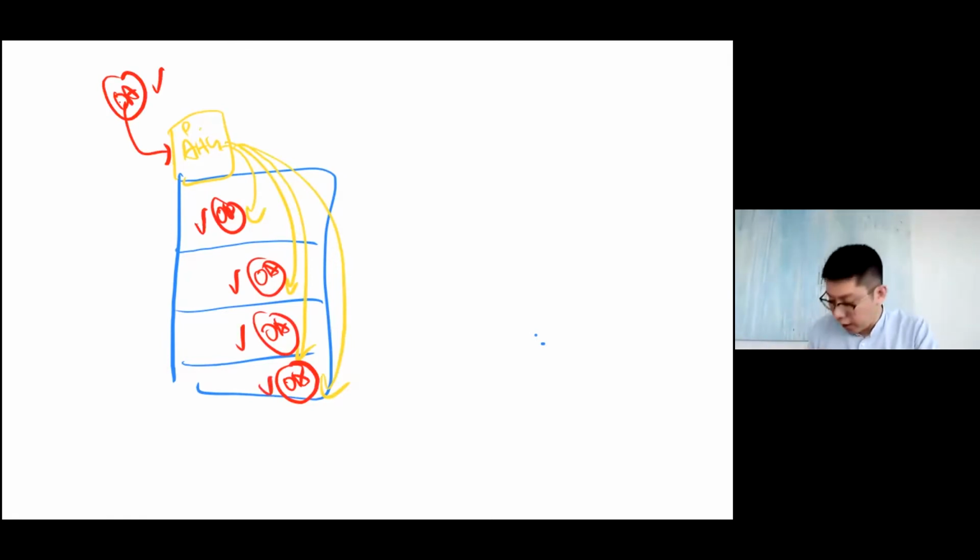So for example, in some of the areas you have the primary AHU serving, but for some of the areas, let's say you can't avoid FCU or split unit. So in this case, let's say this space you have an FCU, and in this case you have some split unit connected outside. The FCU provides local cooling, air going in, going out. So you can actually just ignore all of this. If you have local cooling, all these things don't matter. You still use the 100% outdoor air calculator and input all the OA accordingly.